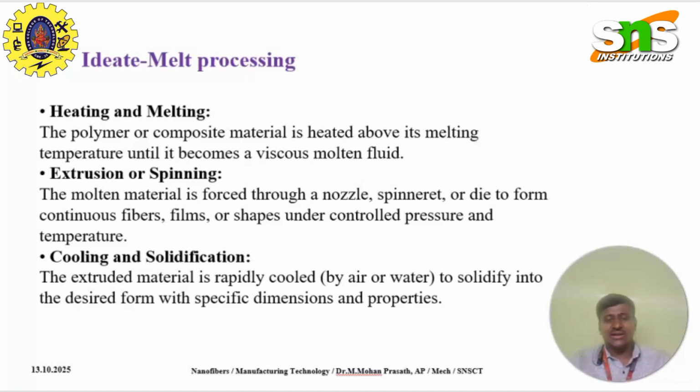The next step is extrusion and spinning. After heating, it is extruded with the help of a die. Next, the final step is cooling and solidification. After extrusion, it is rapidly cooled with the help of air and water to solidify. And finally, it is collected and deposited on the collector drum.